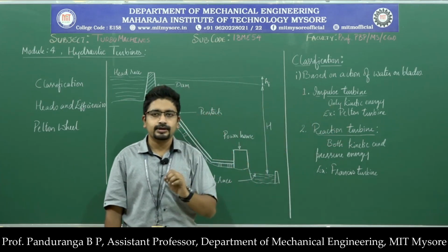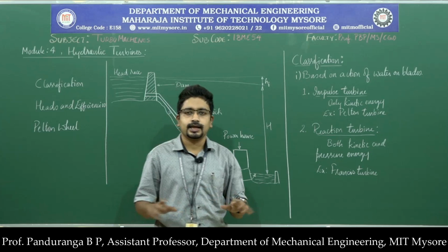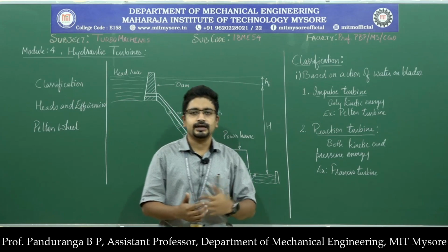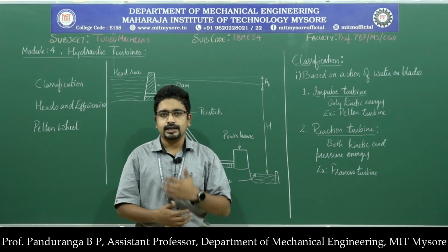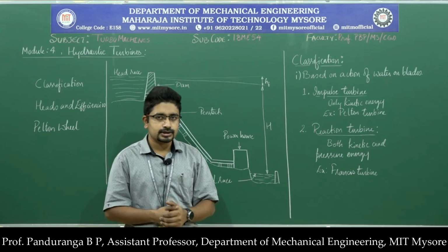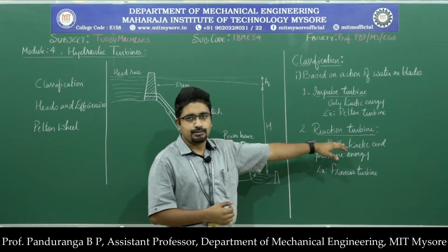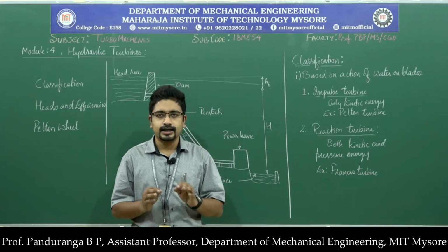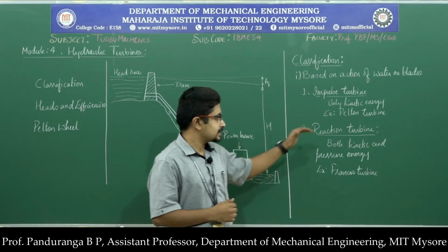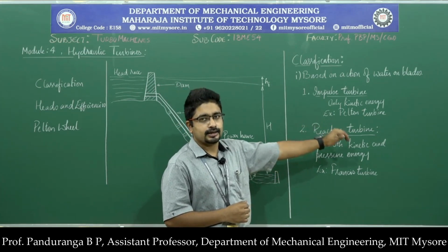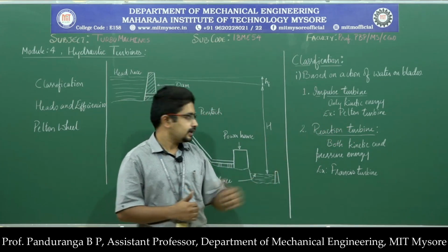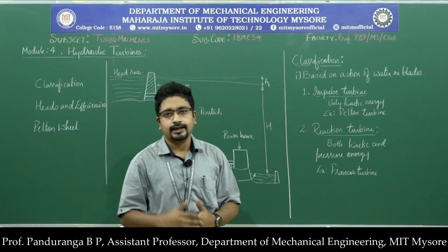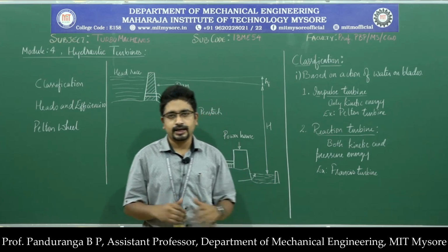In the case of a pure reaction turbine, there will be no changes in the kinetic energy of the fluid, and the energy exchange that happens will be only due to change in the pressure. So, due to change in pressure, there will be reaction force, and those kind of turbines we call pure reaction turbines. But in practical cases, we do not have any pure reaction turbine. Whatever we have is a combination of impulse and reaction turbine. Hence, here the kinetic energy as well as pressure energy will be converted into mechanical energy. So, we do not have a pure reaction turbine.